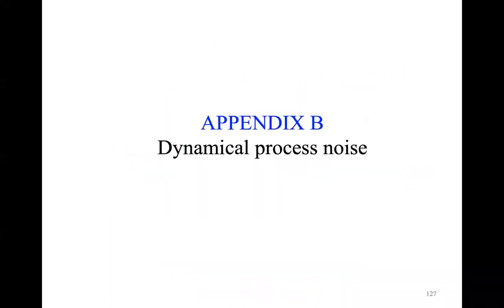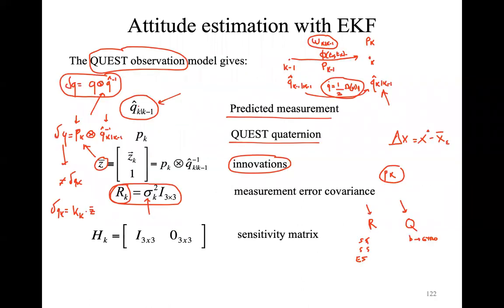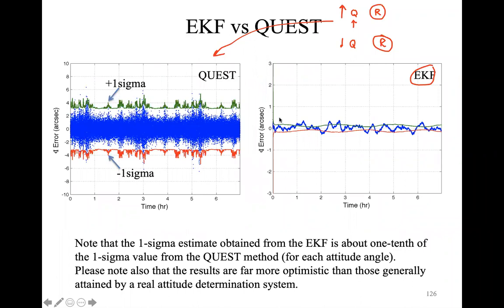What I would suggest, and this was one of the questions that I received yesterday, is to try to tune your filter with different possible values of Q. That could be a good exercise, not for realistic simulation of course, but for academic purposes: try to change Q, for example with a Monte Carlo, starting from a larger value down to a value close to R, and see which values of Q provide the best fit of your Kalman filter.